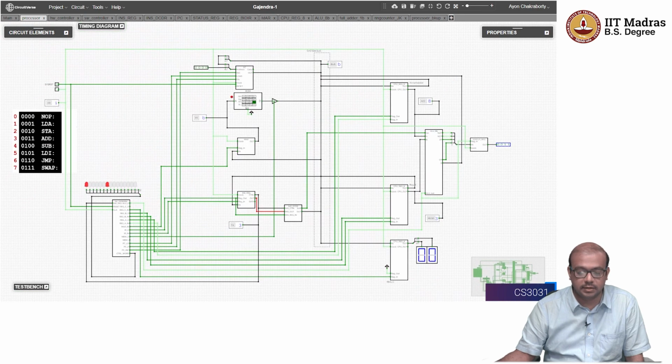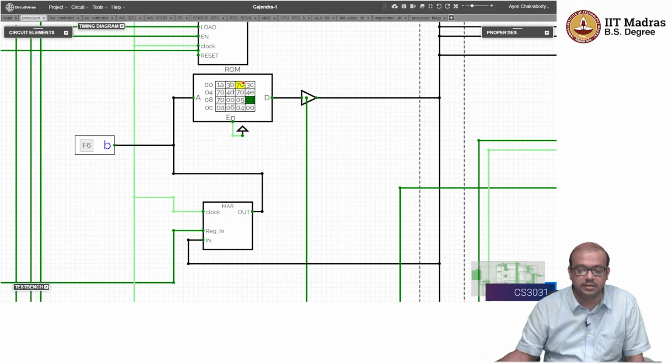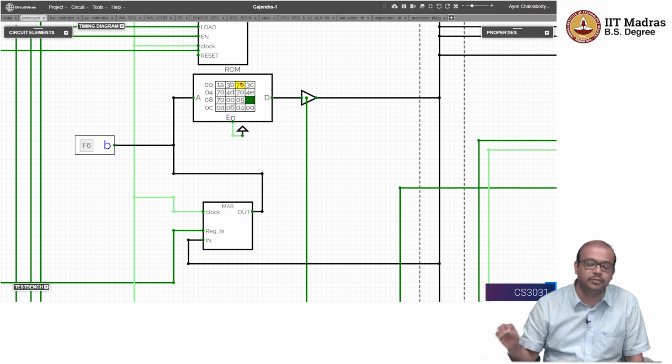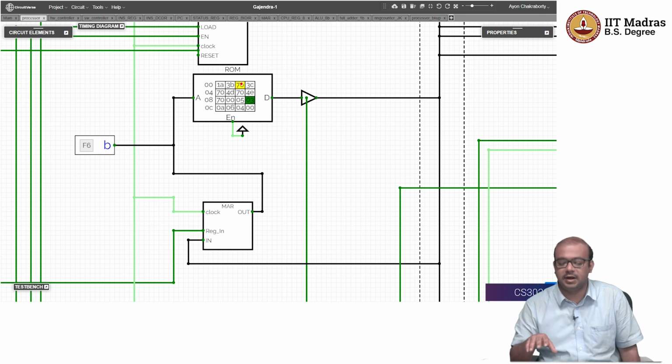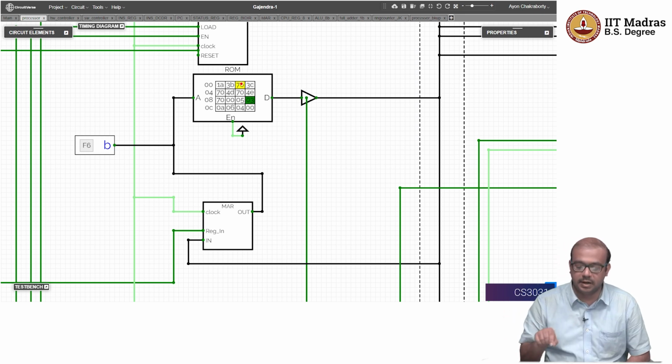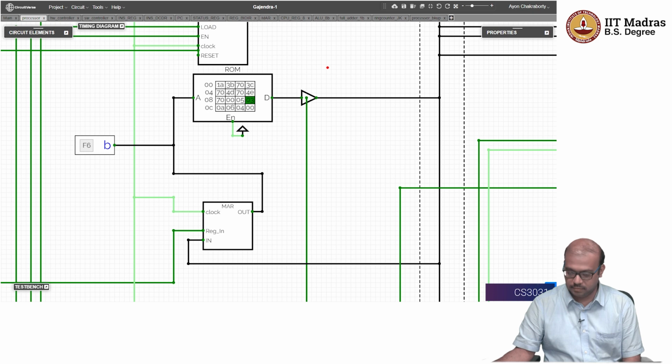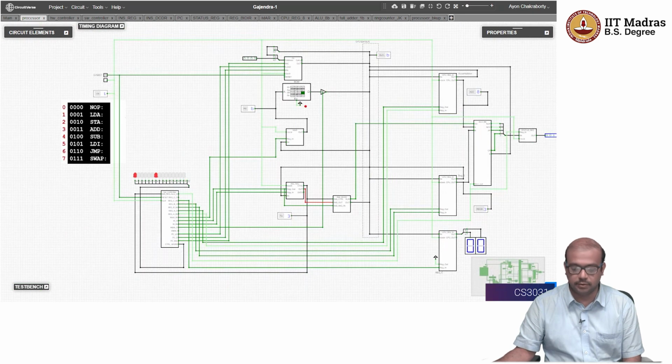So if you see the next instruction, which is 70, I told you, 70 is simply going to transfer the value of the accumulator to register C, and if there is something in register C, the register C dumbly shows that, right? There is no specific control that I have made. In this particular implementation that I am currently showing, if I issue this command 70, A's value, which is 8, is going to be loaded in the register C and is going to be displayed. So let us try that.